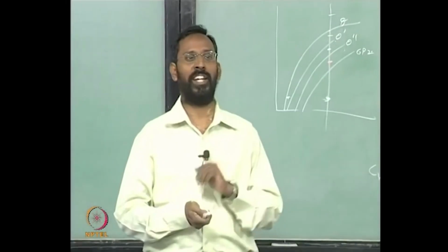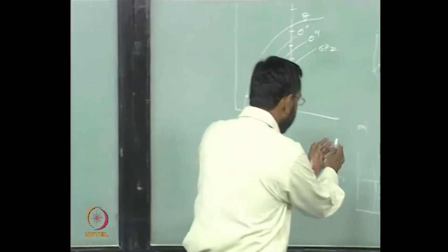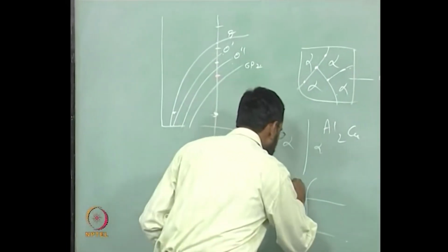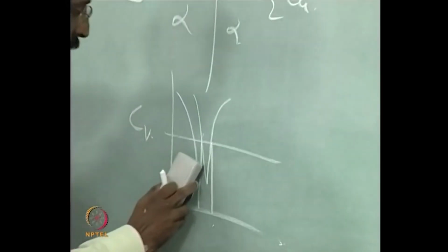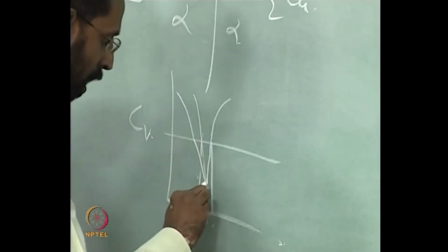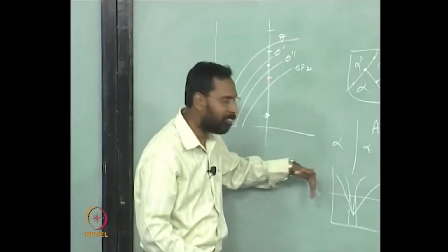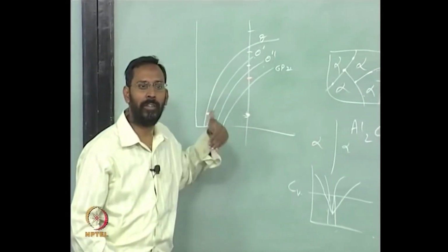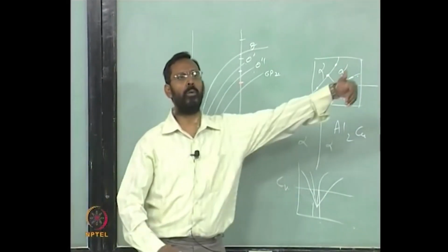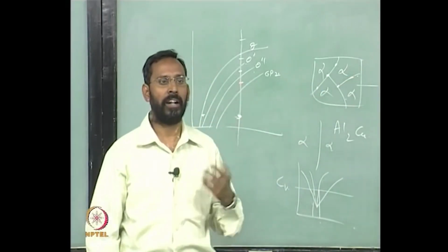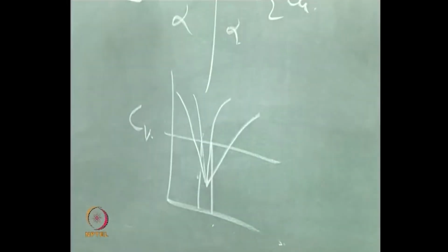Sometimes if you are quenching slowly, then this region is going to be larger. So you may see something like this. That means there is enough time for the vacancies which are farther from the grain boundary to also migrate towards the grain boundary and get merged or annihilated into the grain boundary, and if that is the case, then you would see the PFZ will be larger.